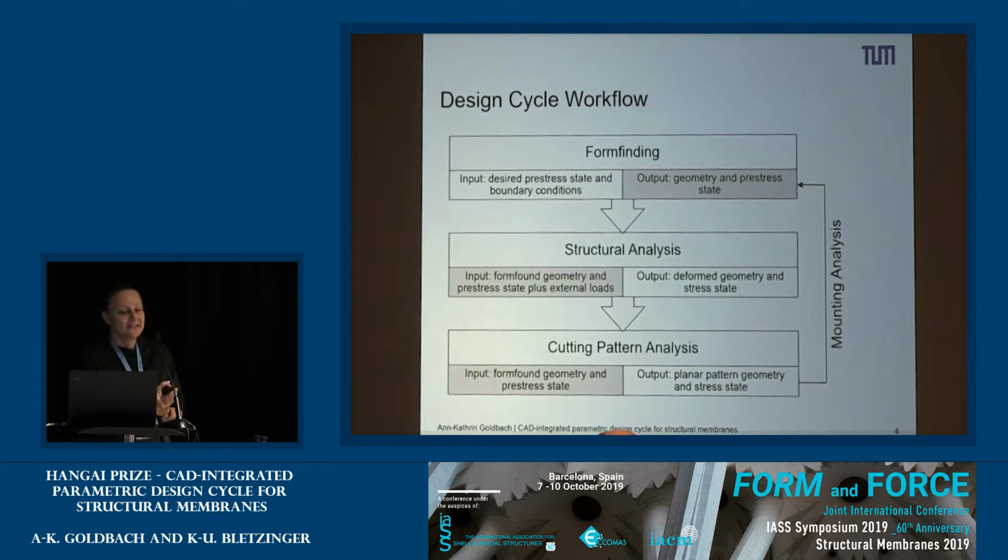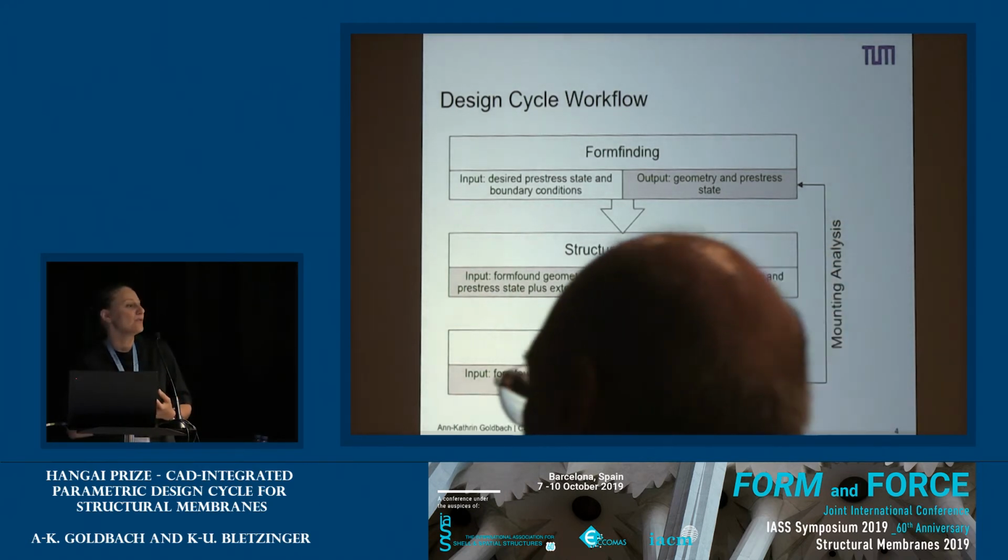Now, if we look at this design cycle more in a workflow kind of way, we can see that the output from form finding will serve as an input for structural analysis and also for the cutting pattern analysis. So if I start thinking about the finite element approach and the modeling, it would be really nice to use one model, have a form found one, and then sort of recycle it for structural analysis and cutting pattern analysis. And that's the idea of the CAD integrated workflow.